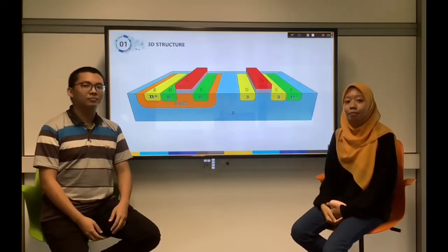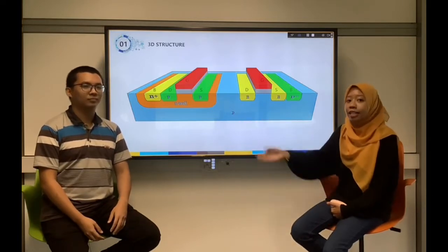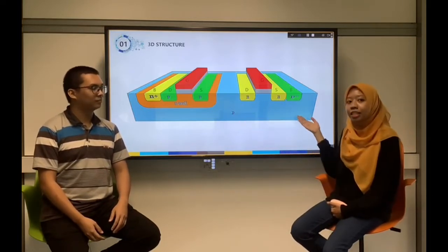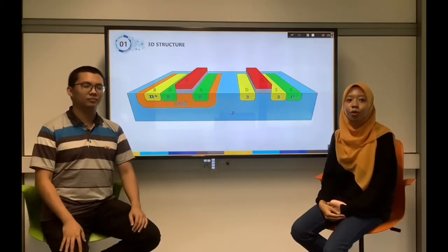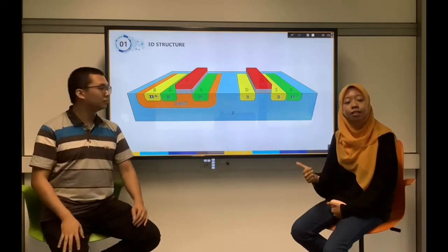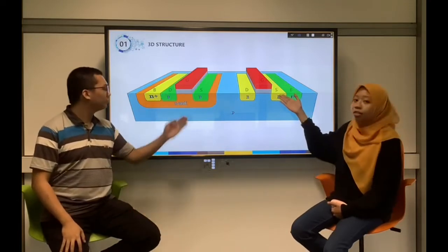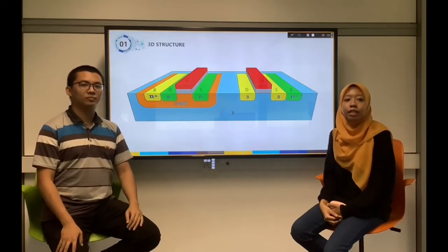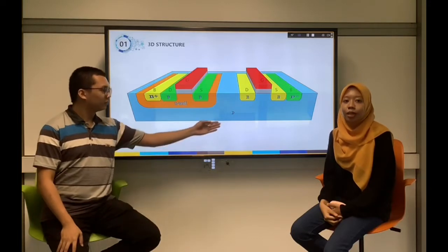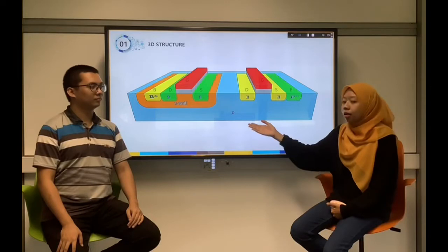This is an example of CMOS with P substrate and N-well. The left part here is the PMOS and the right part is the NMOS. Just like the normal NMOS and PMOS, both of them have a gate terminal, source terminal, and drain terminal. The thin outside layer here acts as dielectric material. The only difference is that both PMOS and NMOS are now on the same substrate. We can see that the PMOS is built in an N-well on the P substrate.